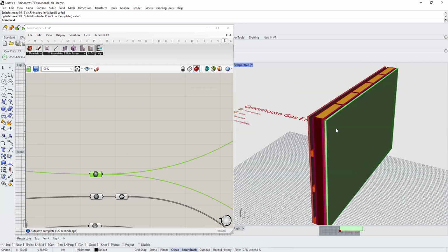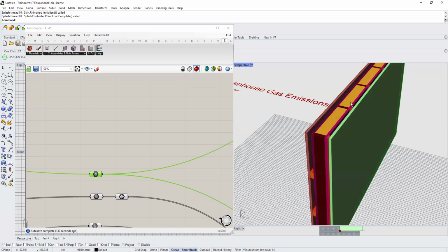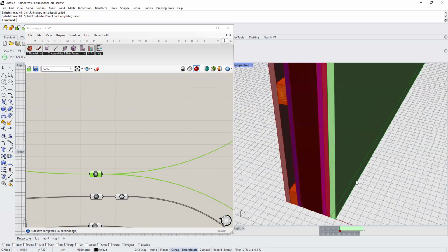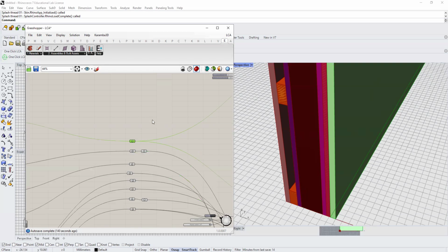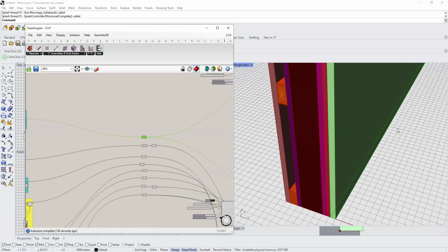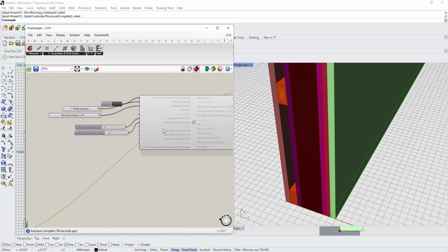In this model, I actually created solid matters. So I mean that this layer is basically an extruded profile, which is the thickness of this cladding. And I created this through, of course, a parametric model. You can actually create this thickness in Rhino viewport and extrude it and transfer that geometry through a geometry parameter in Grasshopper.